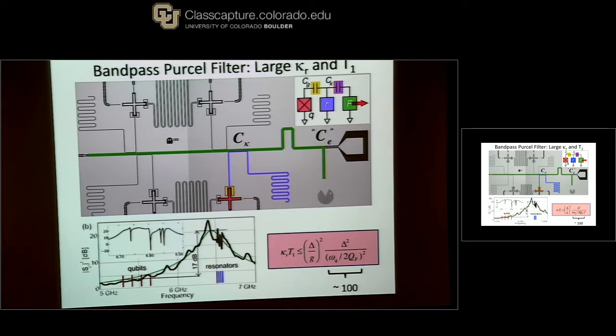Yes? So how many qubits can you measure simultaneously, and what's the limiting factor? Yeah, so the 9-qubit device I'll talk about, recently we did 9. And 5 of them were coupled strongly and 4 were coupled weakly. Right now we're designing around 6. So it's not a huge number, but you can't do a huge number because you have to read them out fast. So you have to have a relatively fast bandwidth, and that just gives you the frequency crowding. But since measurement is complicated, that factor is really useful. It's good. But it can't be 100, for example. I don't see how that would work.